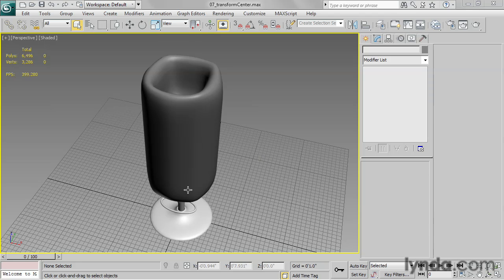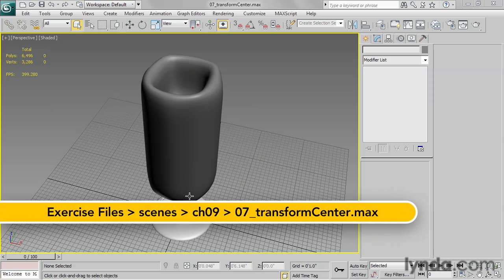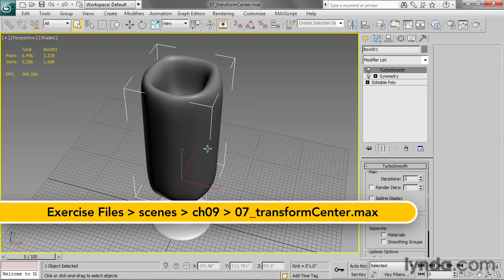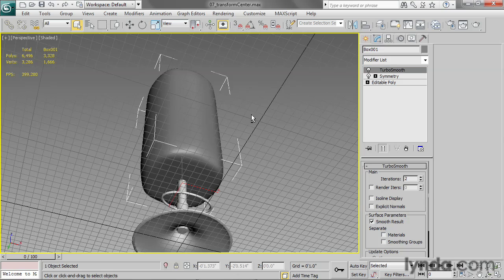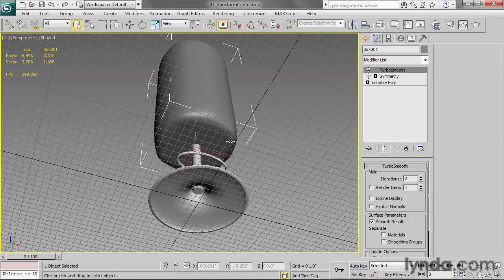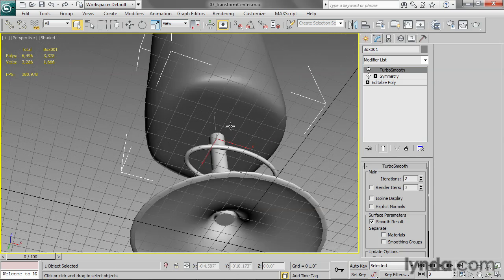Now we're ready to taper the shape of the subdivision surface model to get that bar stool that has that elegant shape to it. What I want to do actually first is to delete the bottom polygons, and that'll give me a much cleaner edge at the bottom here.